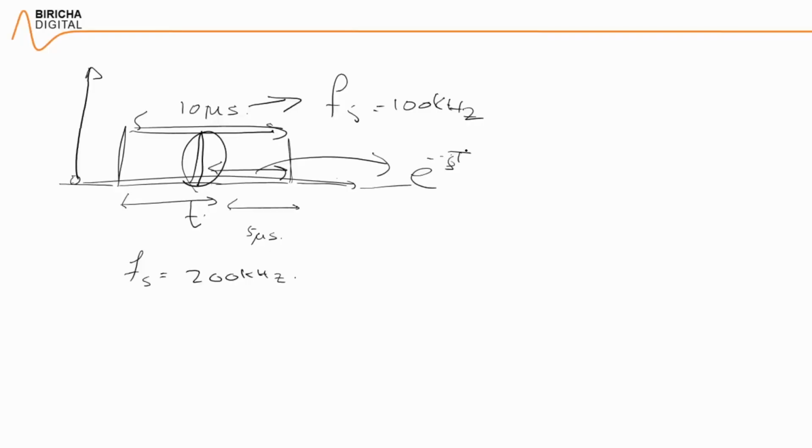But what you have done effectively is you have added a pure time delay into your control loop. However, in analog, you are not capable to change the control loop performance. In digital, what you will do is as soon as you skip this pulse, you also change the control loop performance in order to make sure that now the control loop expects 100 kilohertz switching frequency as opposed to 200 kilohertz. You can have intelligent phase shedding under low loads.